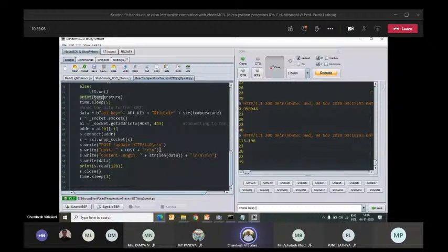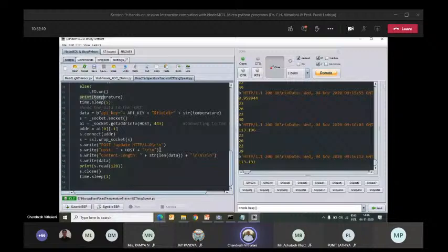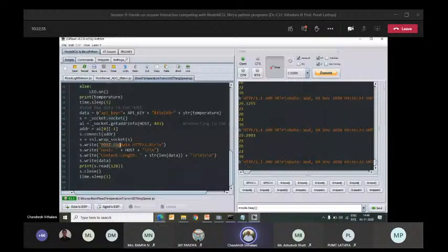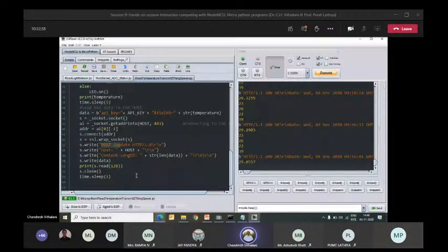So depending on what sensors you are connecting, ultimately you need to change the sensor here at the A0 pin, and then it will produce the corresponding output, and it will be broadcasted to ThingSpeak. So here it is using the API key and the corresponding name of the field, that is the temperature, and establishes the socket. So it is socket programming, and it will broadcast. It will post to the ThingSpeak API. So constantly you will get the data on this cloud.